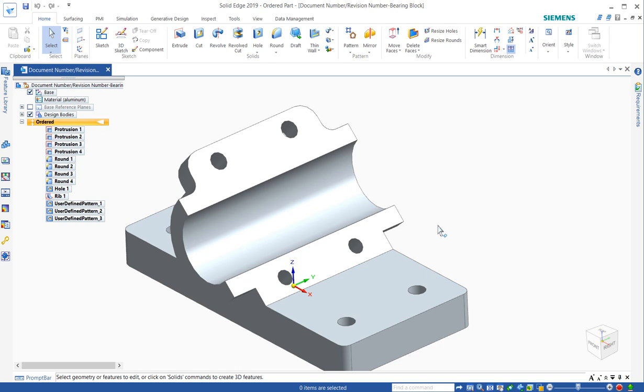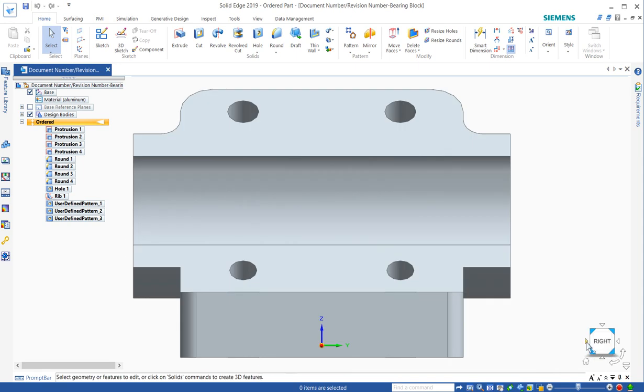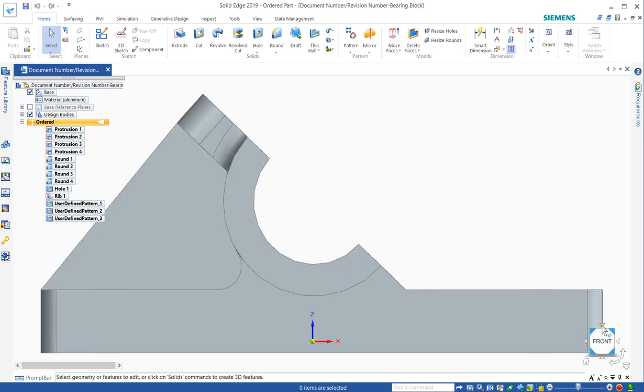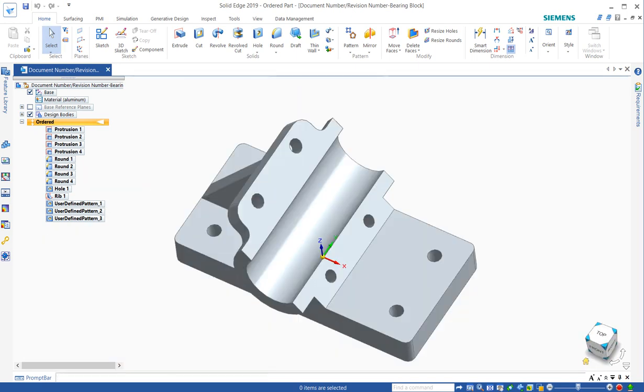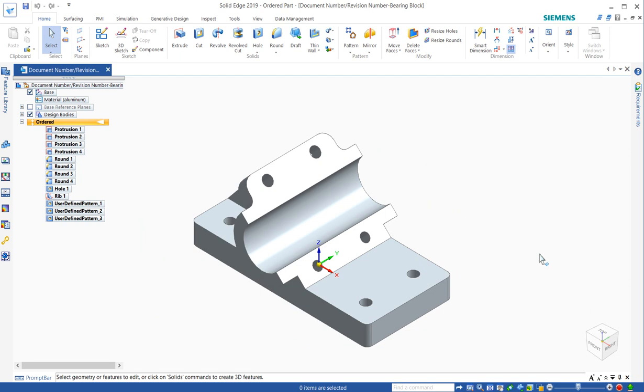There is a setting to change the zoom direction of the wheel. You'll find a setting in the options. There's a rotate about a point. There's sketch view, and there's also this view cube, which I think you would easily just discover on your own, and it's very discoverable. You can just kind of poke at it and discover what that does.